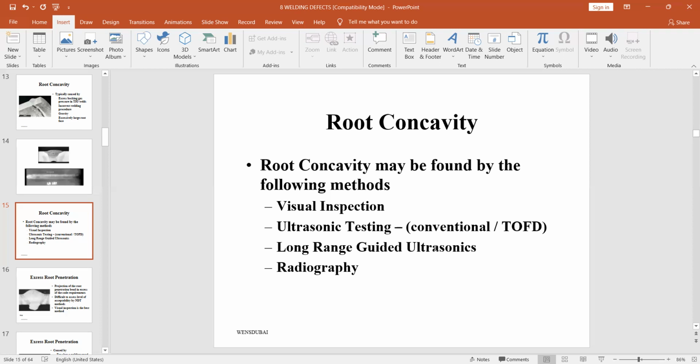So they remove the insulation at a particular area, and we keep the probe there. That is long range UT, not like our normal UT. And you will get any indication up to 5 to 6 kilometers also. So that is known as long range guided ultrasonic testing. Basically they use it for pipelines of gases or petroleum based products which are under insulation.